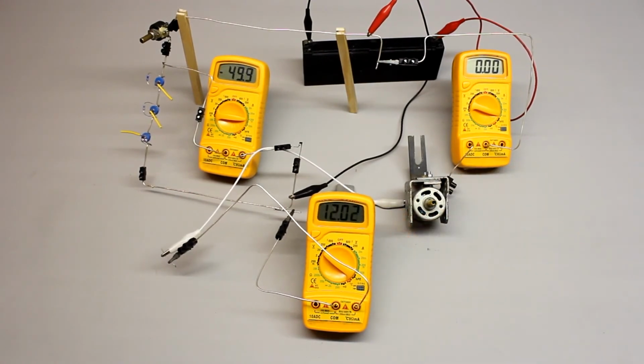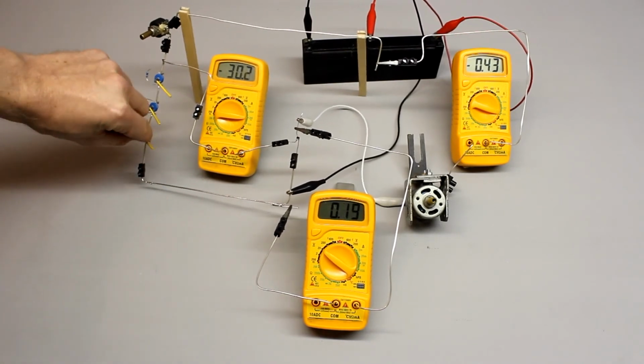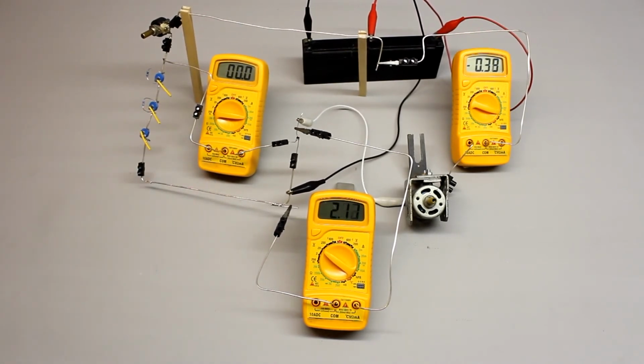Now a very high current is running through the transistor, which is why the device is heating up strongly, leading to the melting of the solder. After resoldering the collector pin, you can see that the transistor has been destroyed by the high current. Even though there is no voltage applied to the base pin, a current is running through the emitter collector line.